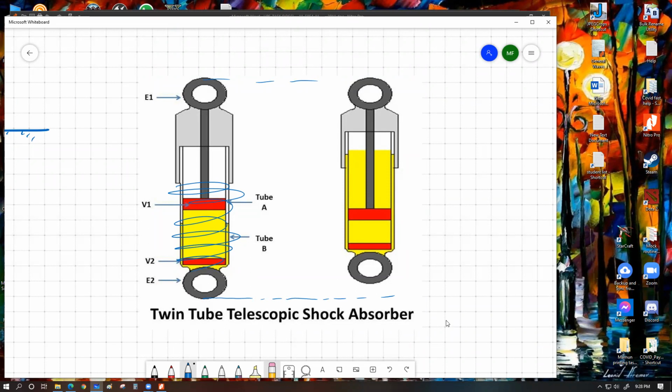It works. So whenever it is pushed down from the bottom, this spring will undergo compression. This spring is attached to this sleeve with a certain type of knob with this link. One end of the spring is stuck with this cover, which is the top cover, and the other end is physically attached with some extension of the inside cylinder. So whenever the shock absorber goes down, this spring becomes compressed.